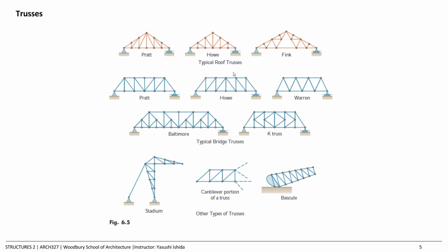So these are various different kinds of trusses, some of which we are going to analyze to determine what internal forces are in each member. These are diagrammatically shown. You can see these two-force members, and all these round nodes are pin joints, meaning they have zero resistance for rotation. It just puts two members together, right?